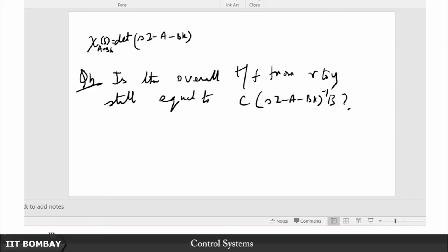Now in today's lecture we shall see the answer to another question which we sort of triggered in the last lecture. The question was, it's fine to say that the closed loop system has the same poles as the poles of the observer and the poles of the plant plus controller combination, but is it then true that starting from this reference input signal to this output, if you look at the closed loop transfer function, the observer plays no part in this?